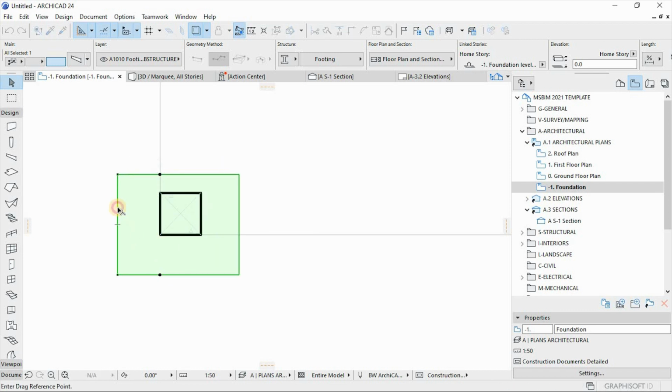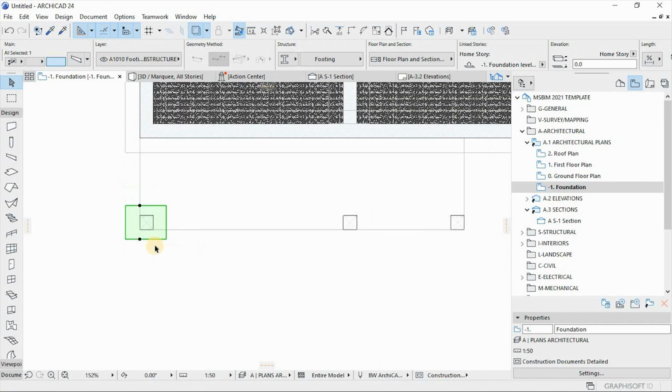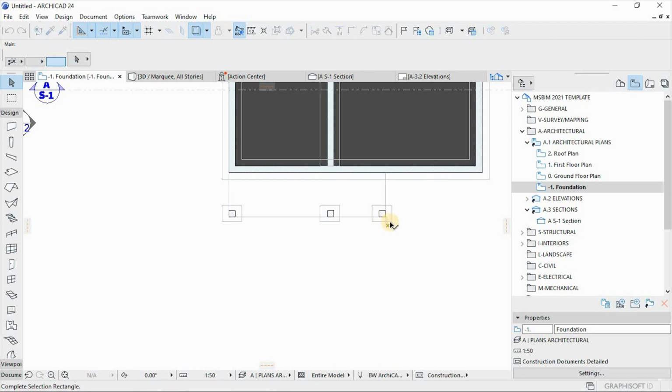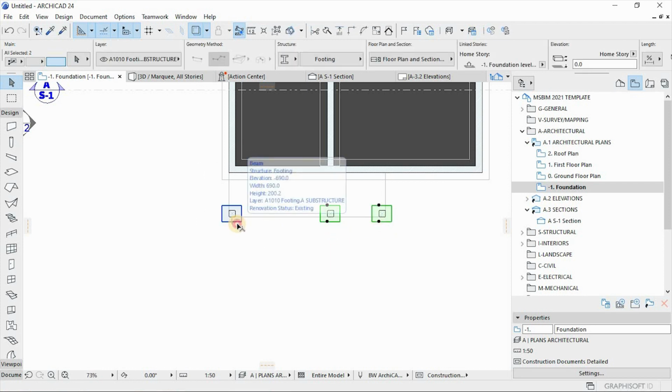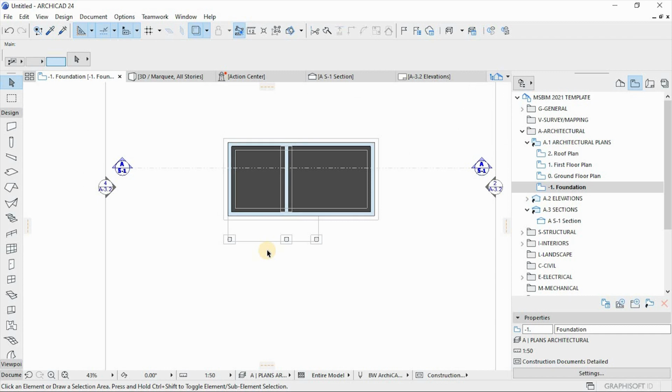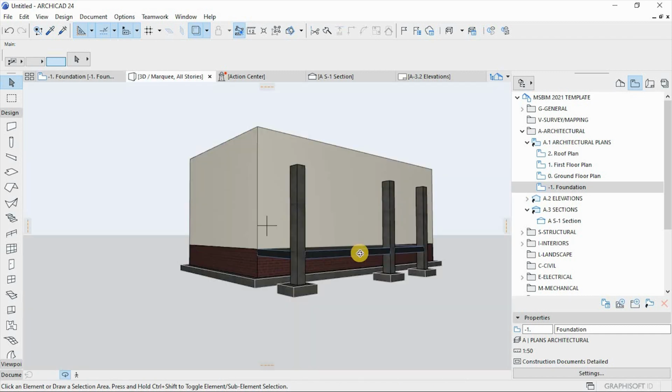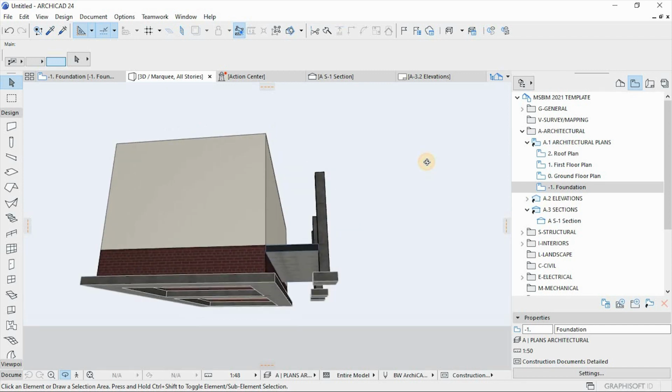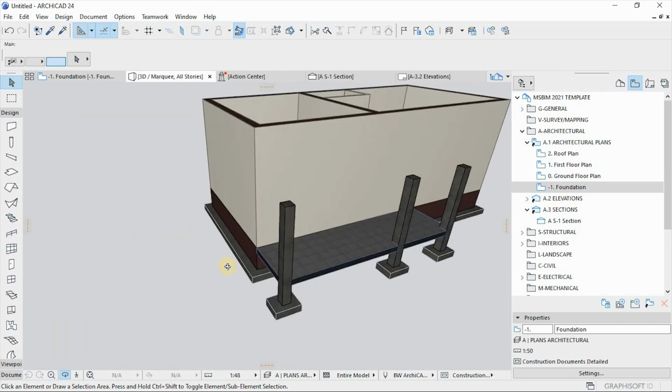Then I'll pick it on the center here, and then I'll also align it with this midpoint of the columns, like center to center, and then Control Shift D to copy or multiply, move to that. But make sure, I like grouping similar objects or objects that are in the same family for easy manipulation and control or management. So this is how it's supposed to be.